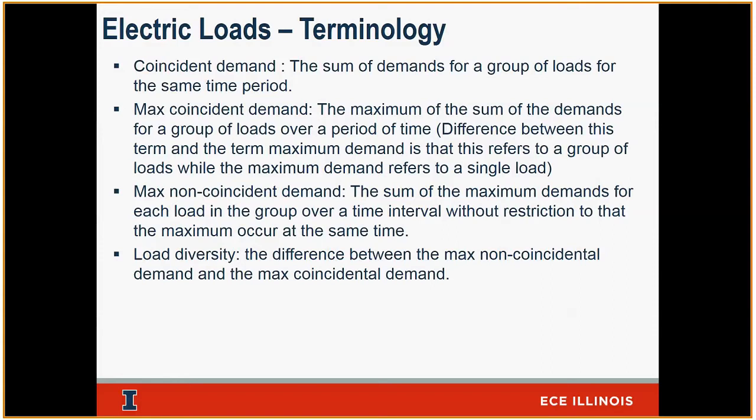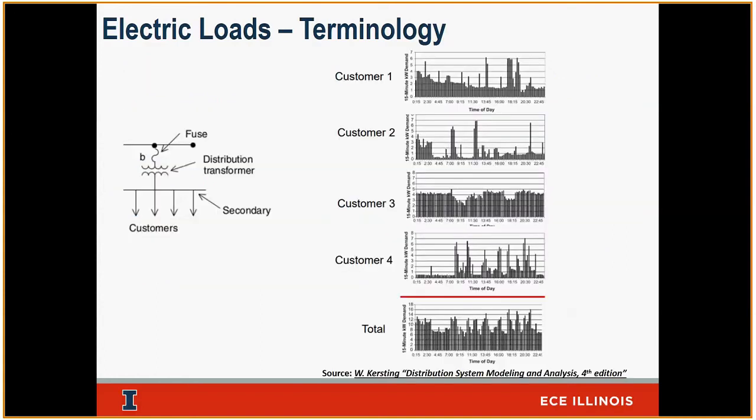Just give me what is your peak overall. What were your peaks at all? Load diversity is just the difference between that max non-coincident demand and the coincident demand. So just how diversified is your load. Here's that example that I was talking about.